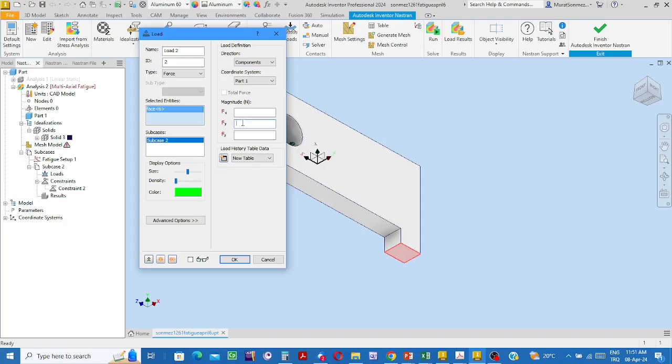Here into this box, write the maximum value. It is 1,000 newtons maximum. Make it distinguishable by having not one vector but a few vectors, so I slid the density slider to the right. Okay, that is the maximum value of the dynamic load.